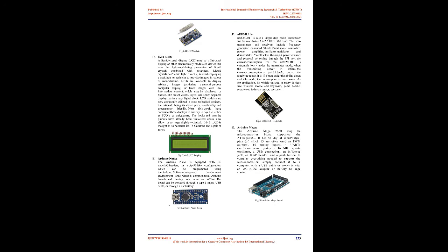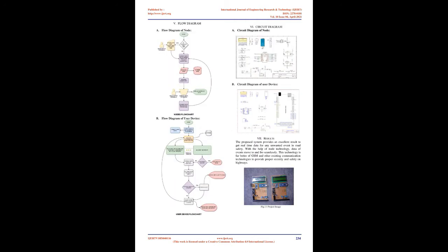C. HC-12. The HC-12 wireless interface communication module may be a new generation multi-channel embedded wireless data transmission module. Its wireless working band is 433.4 to 473.0 MHz, multiple channels may be set, with a stepping of 400 kHz, and there are totally 100 channels. The maximum transmitting power of the module is 100 mW, 20 dBm, the receiving sensitivity is -117 dBm at a baud rate of 5,000 bps in the air, and the communication distance is 1,000 m in open space.